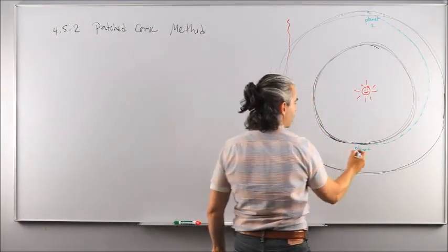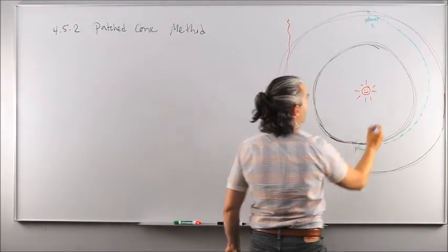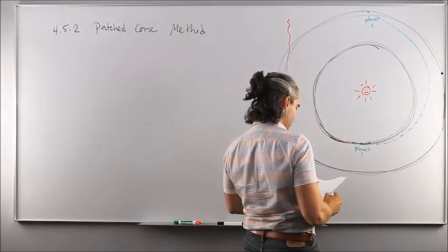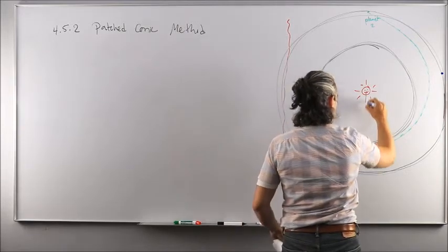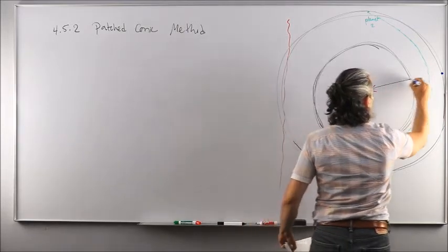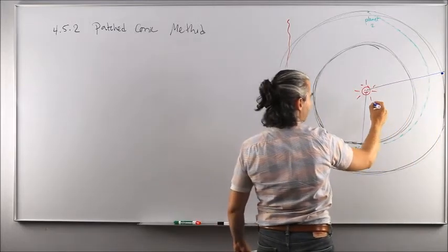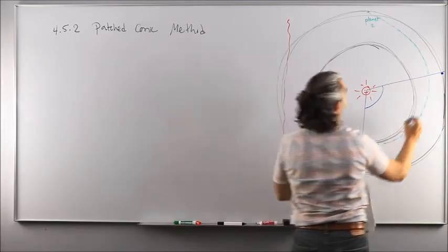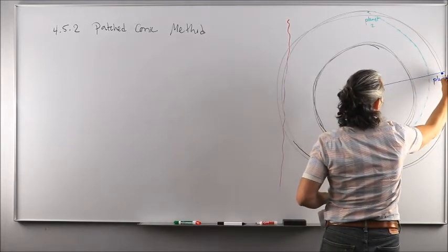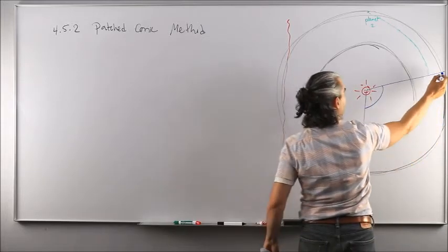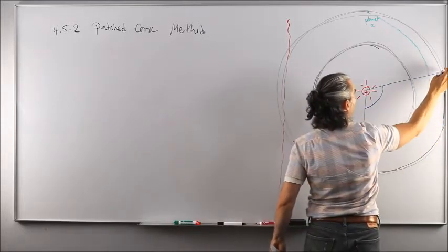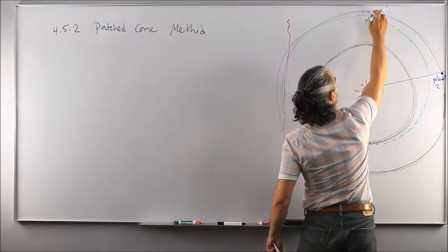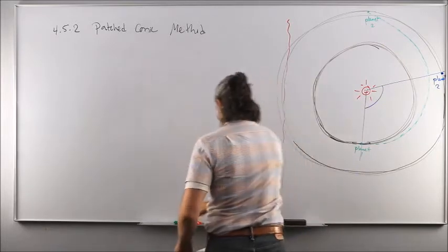So whenever we're going to launch from planet 1, we need to ensure that planet 2 has some position in terms of angle here, such that when we launch from planet 1, planet 2 is around here, and then planet 2 throughout our transfer orbit will have to advance its orbital position in terms of angle to go from here all the way to here, such that when the spacecraft arrives